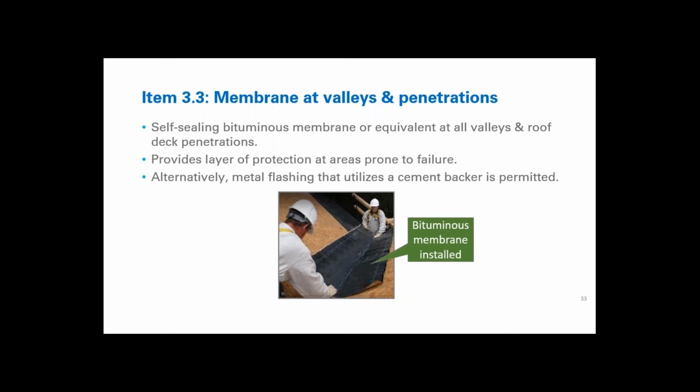Okay, this next item requires a self-sealing bituminous. This is always a mouth twister for me. Bituminous membrane or equivalent to be installed at all valleys and roof deck penetrations. These are areas that have been identified as being prone to failure due to water damage.